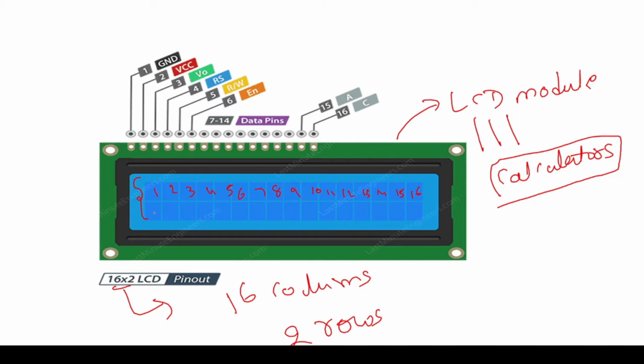So now let us move into the pin diagram. You are going to have 16 pins here, right? The display will come with 16 pins. The first pin here will be your ground pin. Sometimes this ground pin will be named VSS, so there is no need to get confused. If the pin is named VSS, that means it is a ground pin.